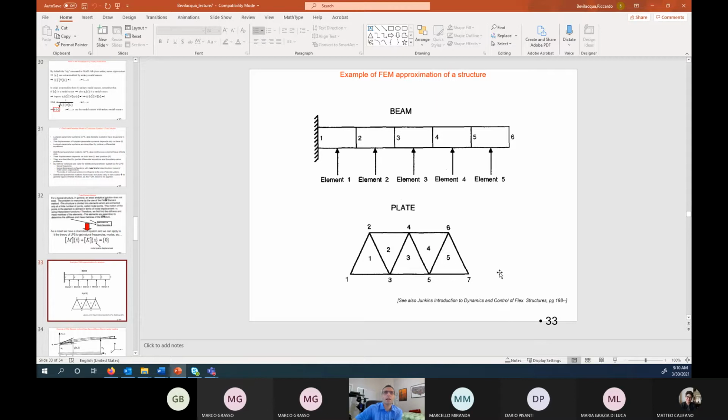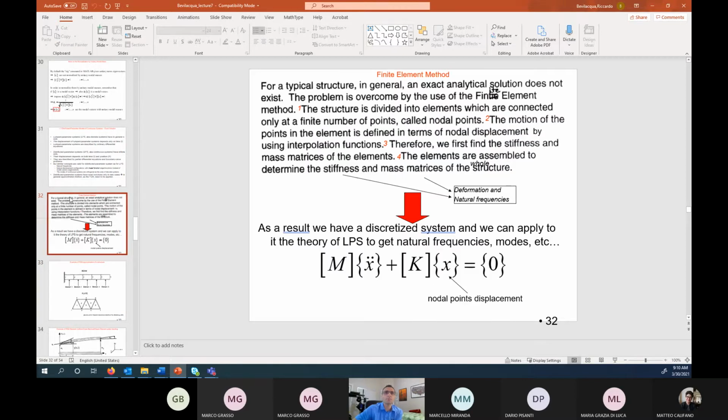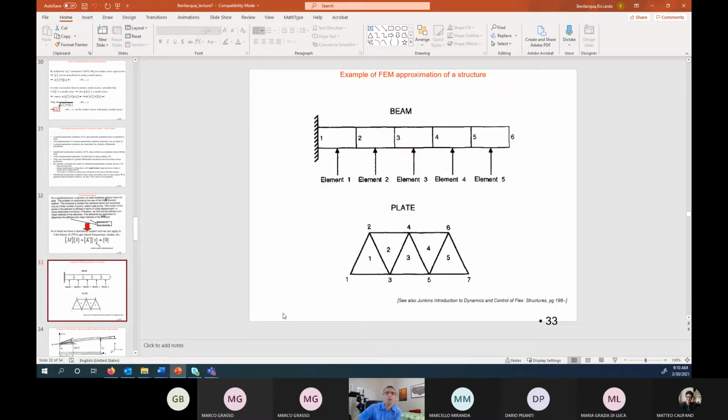And so in my representation, eventually, my mass matrix and K matrix will have to be found so that I can write an equation like this, where the X vector is the displacement, whatever that means, of each of these connection points. And displacement can be an XY translation plus a rotation. It can be many things. So each element can be associated with multiple coordinates.